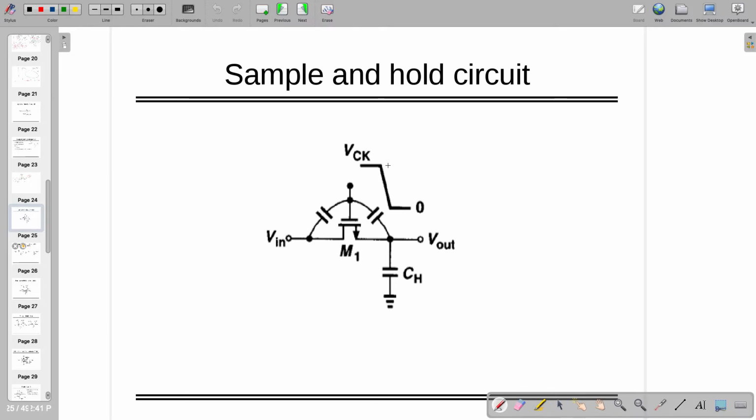When you are going from 1 to 0, there will be some ramp down signal or maybe ramp up signal, which is not going to make this transistor completely off, at least at the transition. So that extra charge, when it's going from 1 to 0 or 0 to 1,